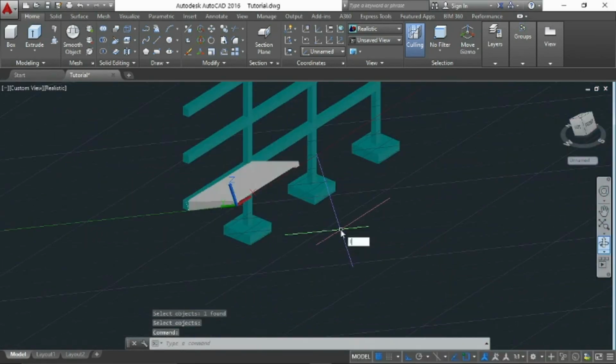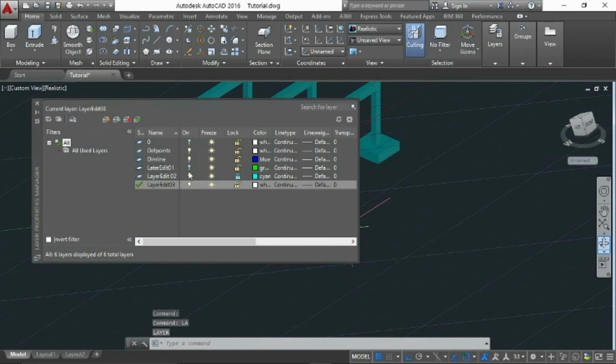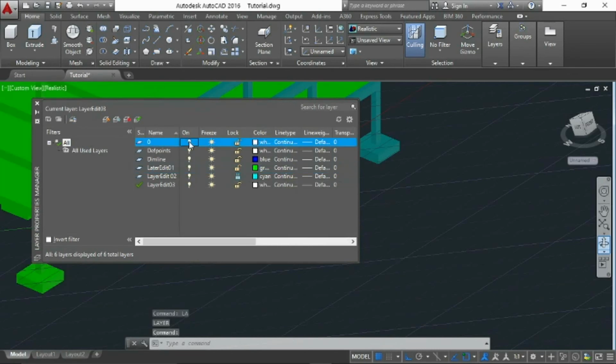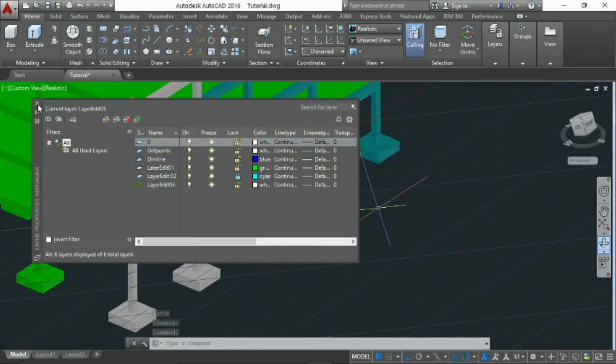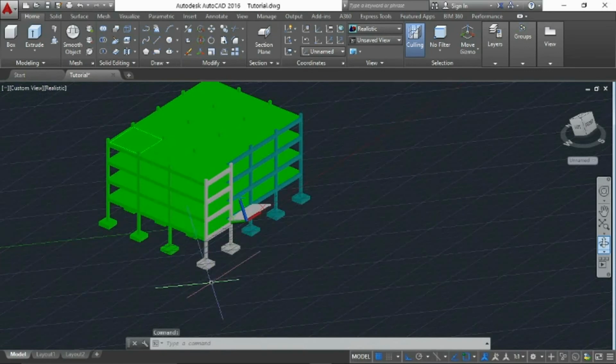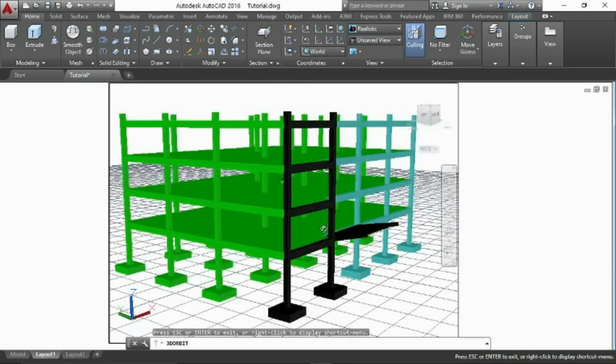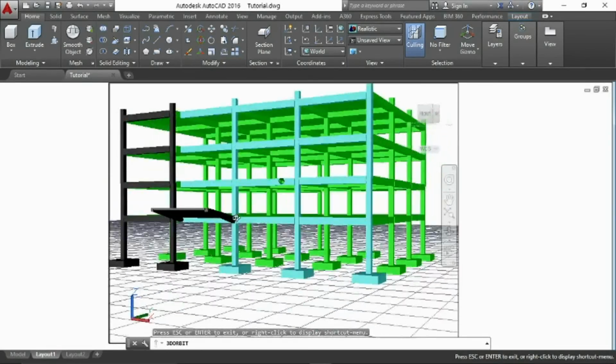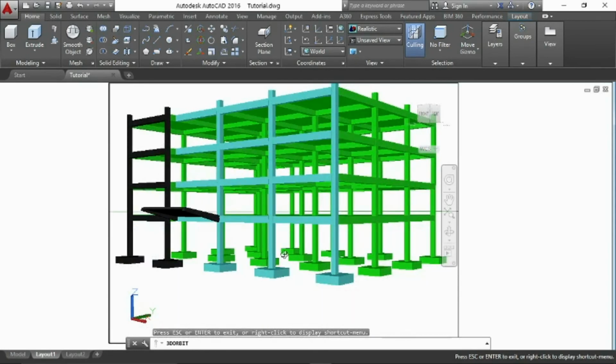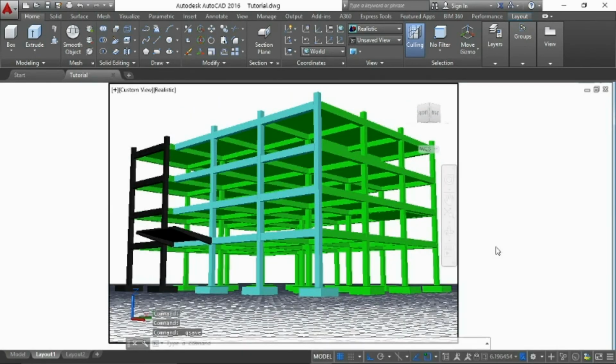So that's it. Let's go to layers. Let's have all the layers on. Close that. Then let's go back to our layout. Let's see what happened to our layout. I think that is better. So there. So that's it. We have slice, rotate, UCS, move, extrude, as well as the use of our layers, how to add new, how to lock, and how to turn it off so it will not be shown on your drawing, so you can do it well.